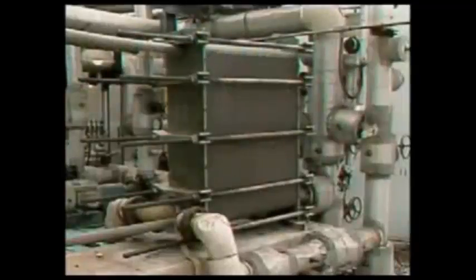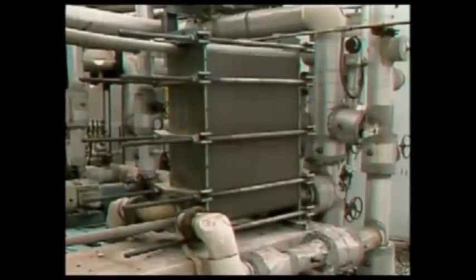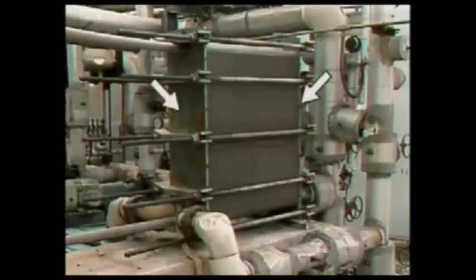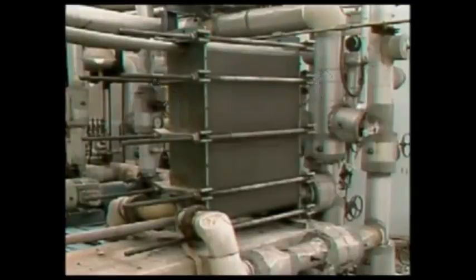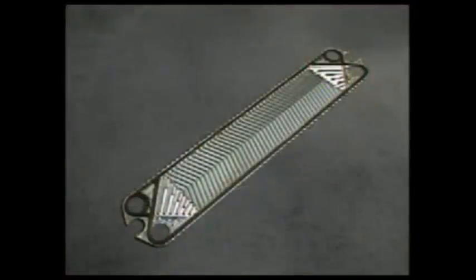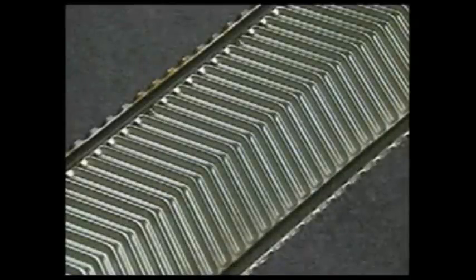All plate heat exchangers work basically the same way. So by looking at the components of a typical plate heat exchanger, you'll better understand how all plate heat exchangers work. This plate heat exchanger consists of a series of thin metal plates and two fixed end plates. The end plates are used to help support the other plates, and they hold the fluid inlets and outlets. The plates inside the heat exchanger have a corrugated or ridged surface. The ridges cause turbulence as the fluid passes over the plate. The turbulence helps increase the amount of heat that's transferred.